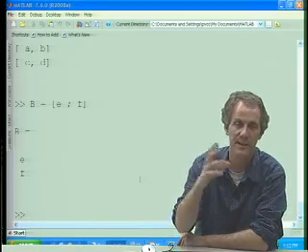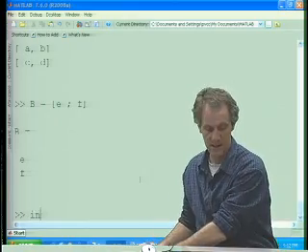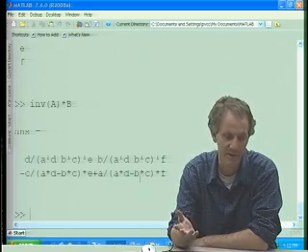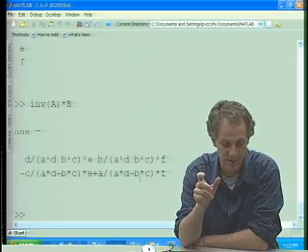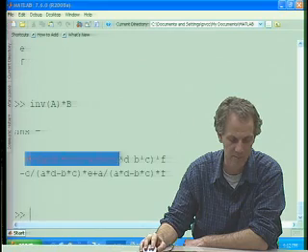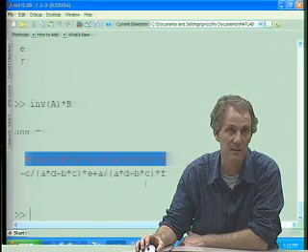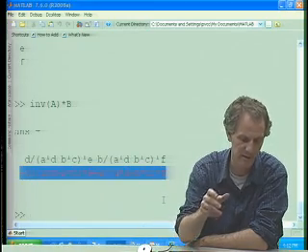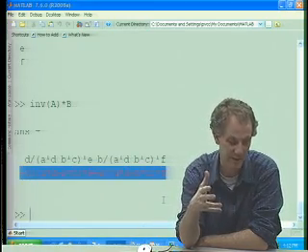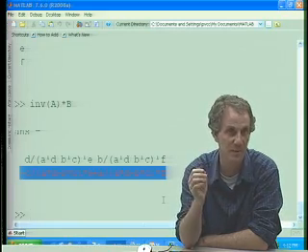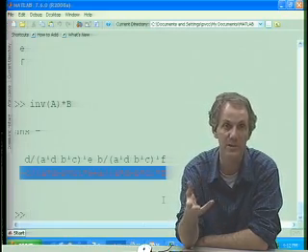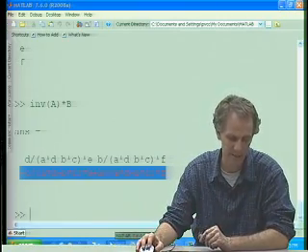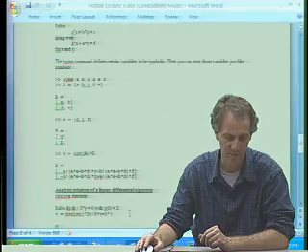So that means I need to invert the A matrix and multiply it times the B matrix. INV(A) times B. And I get a whole bunch of stuff, but actually that is just 2 numbers. The top row is X, written symbolically using those 6 parameters that we defined. And the bottom row is a single number, Y. You can even eval these. There's an eval function that allows you to put numbers in for those and turn that formula into a number. So that's pretty cool. So you can do symbolic work. It's really not MATLAB's strength, but it's an option for you.